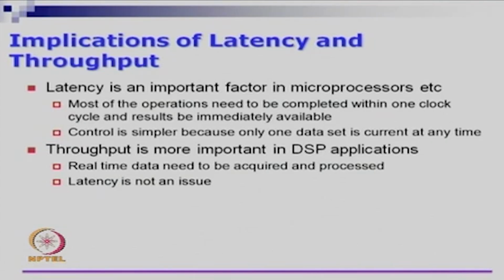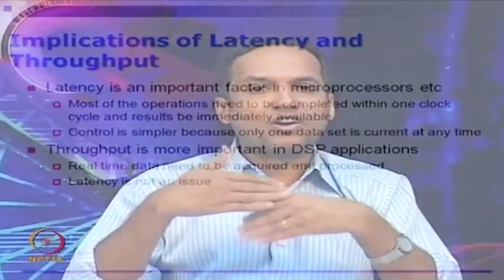So, you have to design a circuit that is really fast. Remember, if you are giving only 1 cycle to do addition or multiplication, then we cannot say I will pipeline it and I will get the results after 5 cycles. We need the result in 1 cycle, the whole thing should be combinational and fast enough to accommodate, let us say, 1 nanosecond delay. That is all you can get for a 1 gigahertz clock used for a processor. If you are using a 3 gigahertz or a 4 gigahertz processor, you are looking at either 0.33 nanoseconds or 0.25 nanoseconds to implement the whole adder, or multiplier and whatnot.